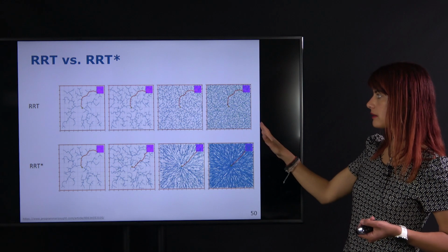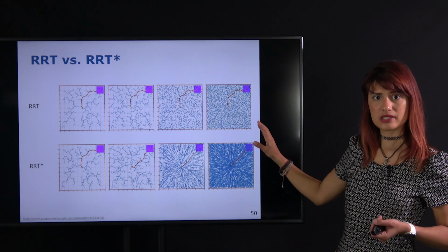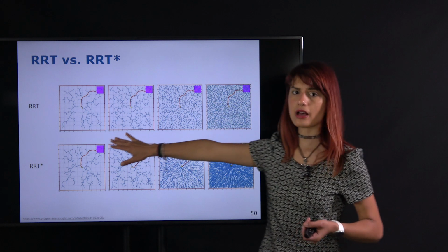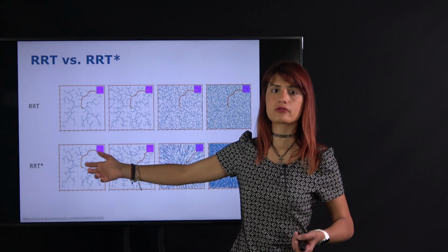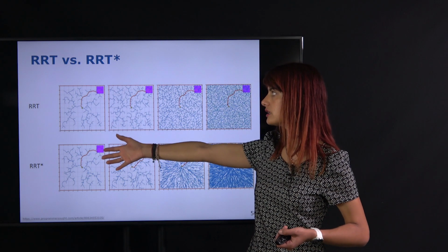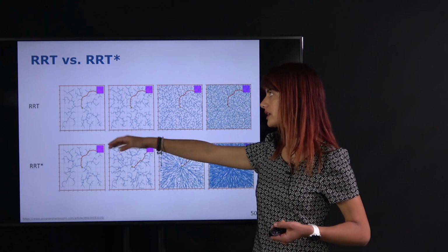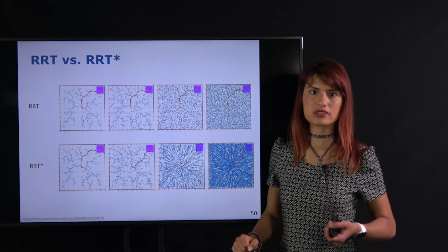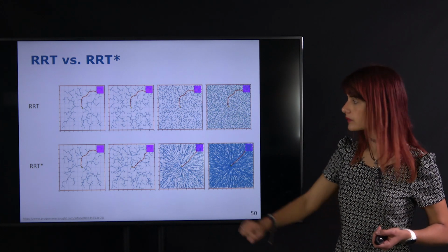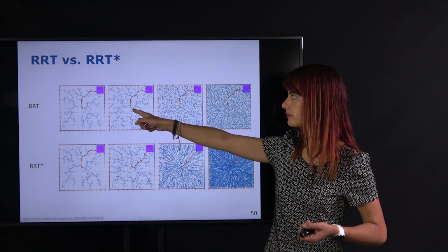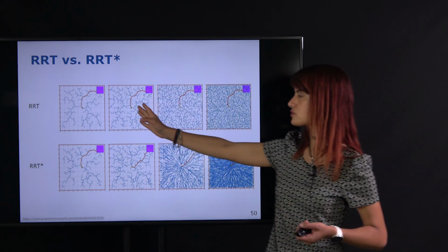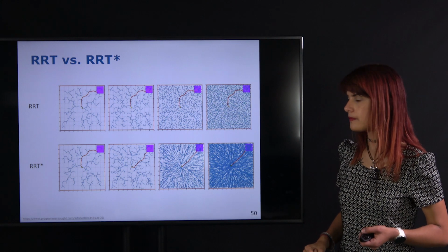Over time, we get a very dense coverage of the space, but we cannot update the path that we already found. This is because we don't have mechanisms for rewiring the tree or sampling in a smart way to make sure that we get the shortest possible path. And so the path kind of curves out and does not correspond to a very straight line connection.